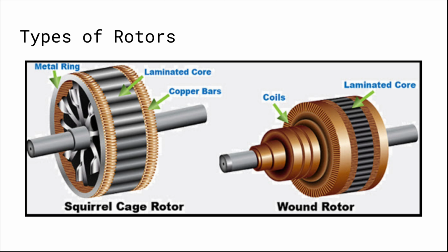The rotor winding has current induced in it by the stator field, like a transformer, except that the current in the rotor is varying at the stator field rotation rate minus the physical rotation rate. The interaction of the magnetic fields of currents in the stator and rotor produce a torque on the rotor. By adjusting the shape of the bars in the rotor, the speed-torque characteristics of the motor can be changed to minimize starting current or to maximize the low-speed torque.